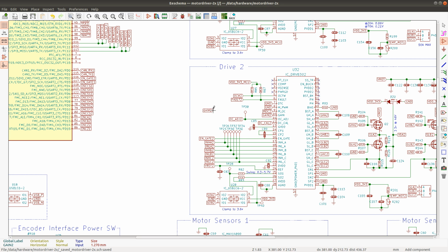So we have gain 2 and DC cal 2. And we can place a test point there. Okay, temperature sensing, of course that should have a test point. Knowing the voltage that goes into the temp sense ADC input is very useful.